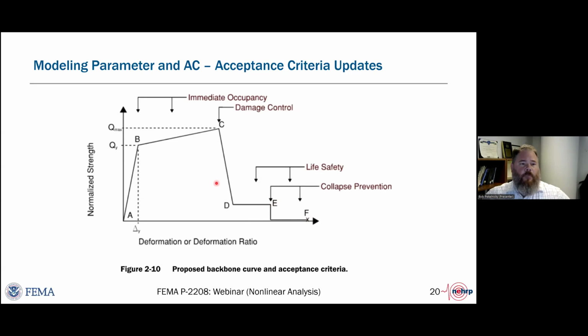But I want to draw your attention to one very significant change in ASCE 41-23's modeling parameters for nonlinear analyses, and that is setting damage control explicitly at point C, as opposed to setting it as a halfway point between the immediate occupancy and the life safety performance level.